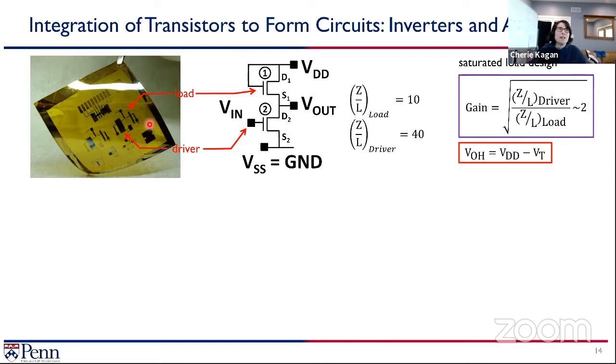But what you see is that in these circuits, what happens in circuits more generally is that in the transistor, you have a gate layer and you have your source and drain layer on top. And in circuits, the key is that you effectively connect different source and drain electrodes to different gate electrodes through what's known as a via. So somehow you have to connect the higher source and drain electrodes to the gate electrodes underneath. And so you have to create pathways or holes, things that are known as vias, vertical integrated access holes, to connect those. And the way that I like to think about this in circuits as an easy way to describe it is to think about it as two floors in a building that are connected by a staircase so that you can control the flow of charge.